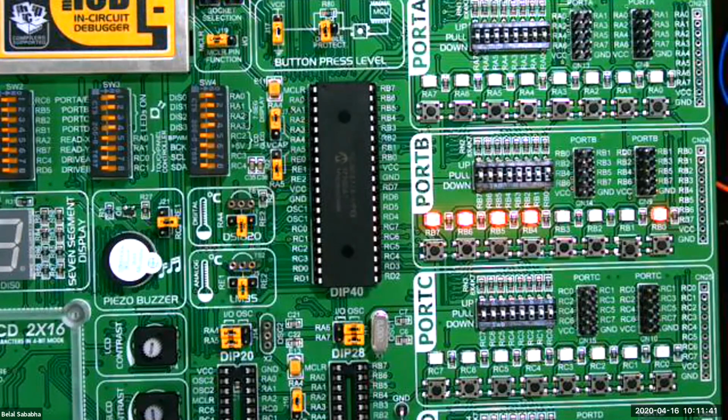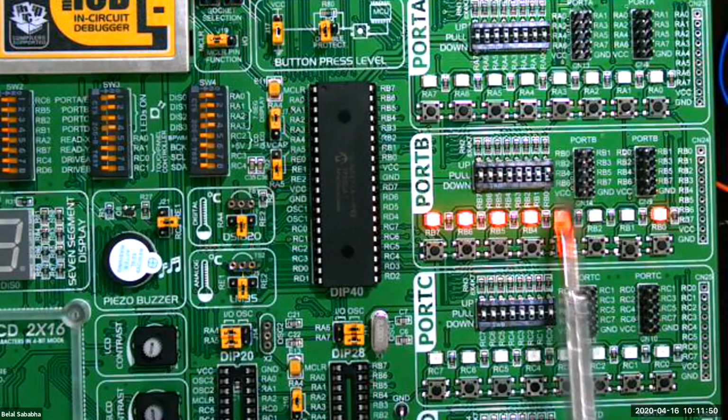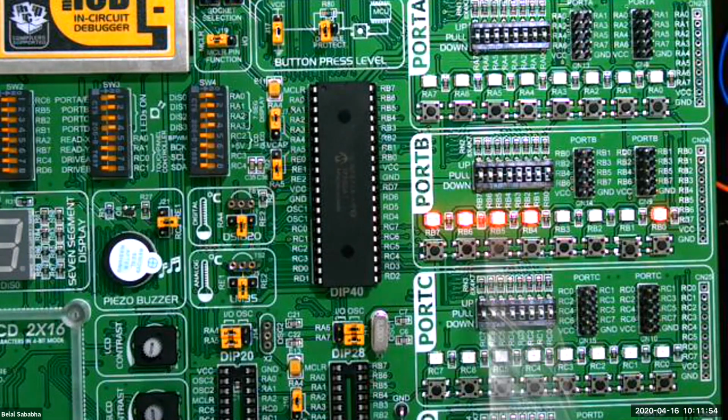And there was a problem when we first started, which was this dip switch on port B0. It was in the middle. So I pushed it up to make it, if you see here, pull up or pull down. So you can pull the button up to high or pull it down to low, but the default was in the middle, floating. So when it was in the middle, it was doing weird behavior where the controller wasn't able to judge if it's high or low.